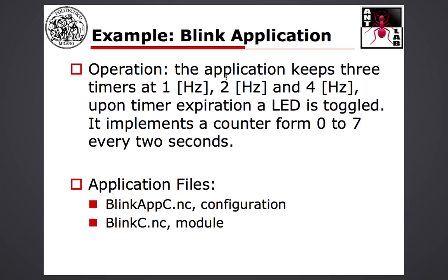That means one timer expires every second, one every 500 milliseconds, and one every 250 milliseconds. Each timer is connected to a particular LED, to a particular color of light. Whenever a timer expires, the LED is toggled on or off, meaning that light is turned on or turned off.